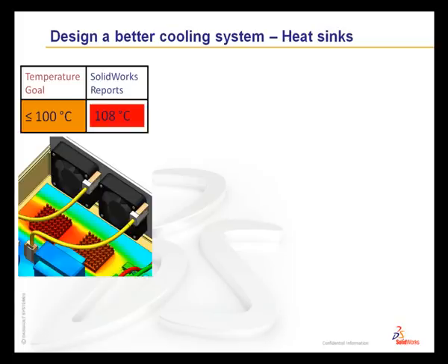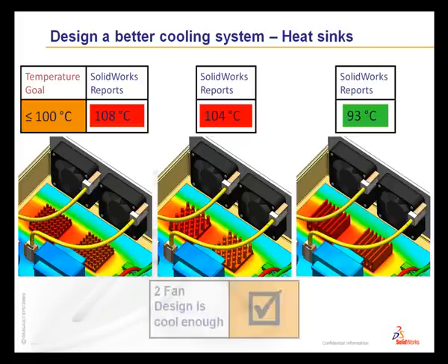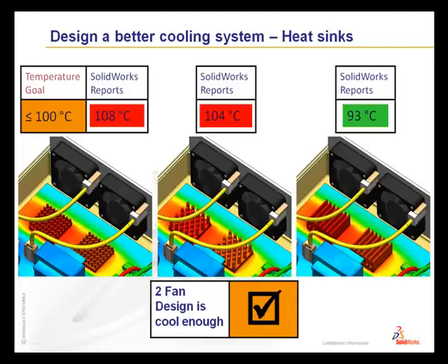Again, defining a different SolidWorks configuration where the heatsink is replaced by a circular pin sink. Running the study shows that we get another improvement. However, this is still not sufficient, only cooling our CPUs to 104 degrees. A final change to the heatsink design delivers the best cooling performance when using the straight vaned heatsink, leaving us with a much improved temperature of 93 degrees C.